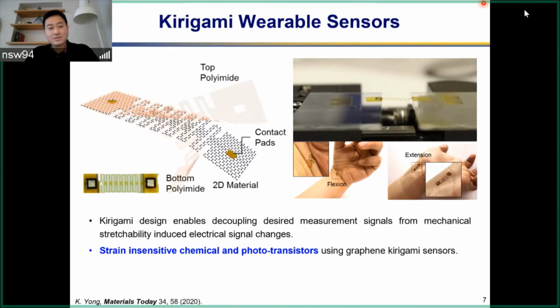And this structure, for some might be familiar, is basically a structure known as a Kirigami. You start with a thick slab of material, and then you introduce cuts to the material so as to enable the stretching ability of this structure. Otherwise, it's going to be very, very stiff when it comes to stretching operation. So that's the structure or device that we have built. And I'll talk a little bit about mechanics associated with this. But let me first tell you what we observed.